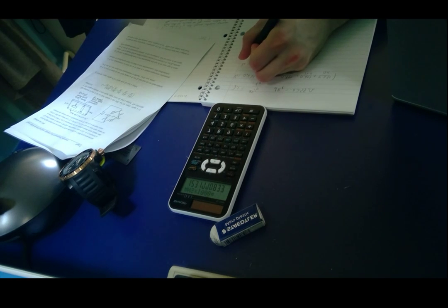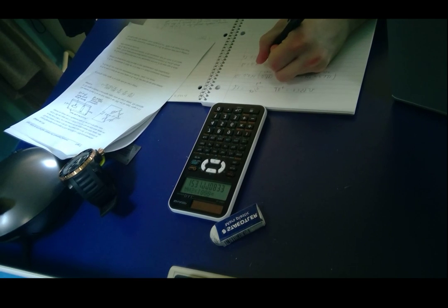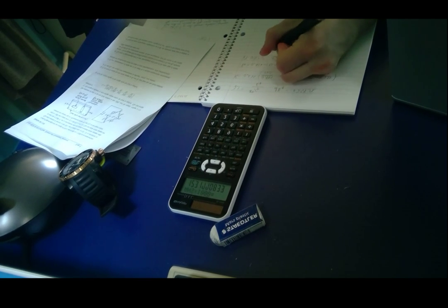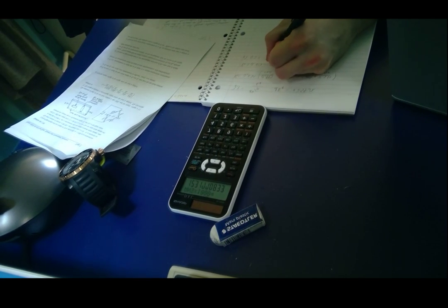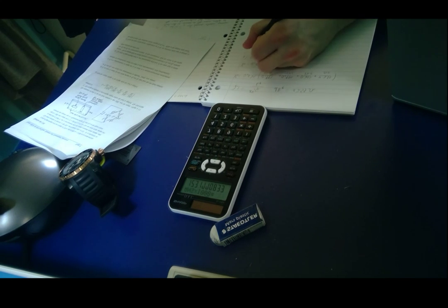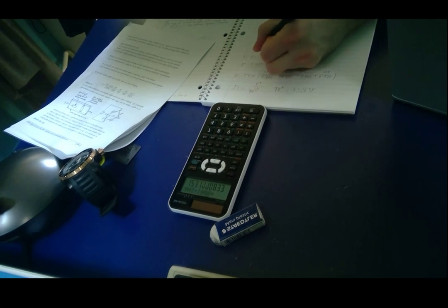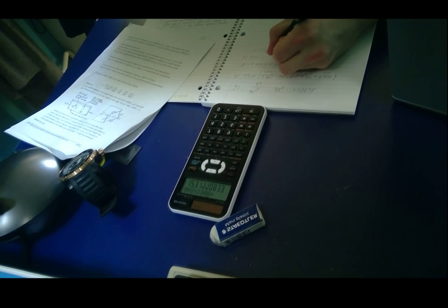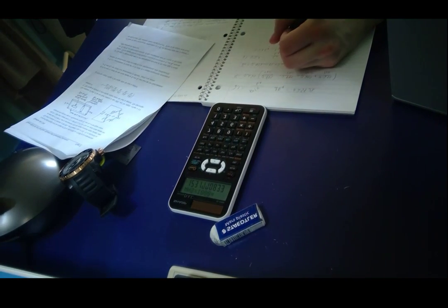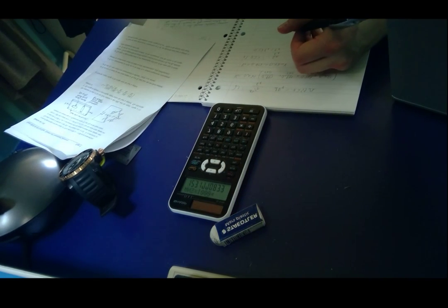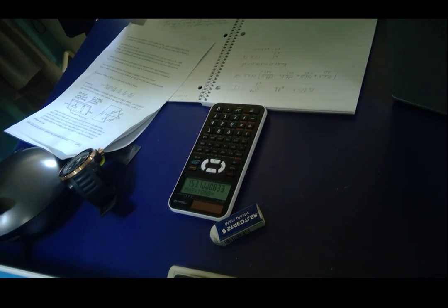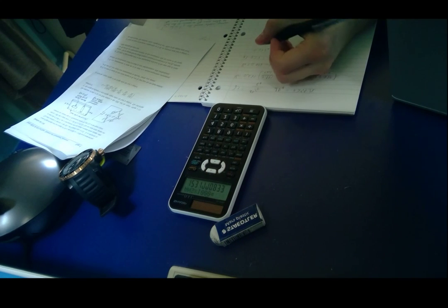So we have the Poisson's ratio 0.27 is equal to minus epsilon t divided by epsilon a. So minus 0.27 epsilon a is equal to epsilon t. Now that we've related epsilon a to epsilon t, we can replace epsilon t by its relation with epsilon a later on.